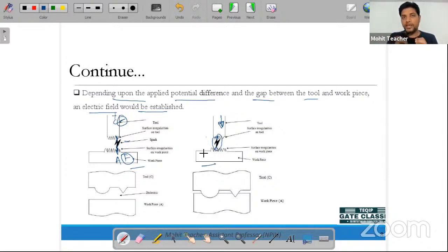Okay, so what we have to do is, if we have to go for the EDM process, then the surface roughness should be managed initially. Surface roughness should be in microns, otherwise if there are irregularities, material removal will start from there and irregularities will form, meaning discontinuities will again form in continuity, because of the irregular shape and size.